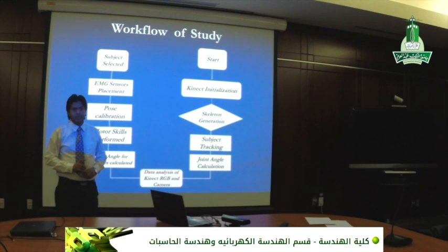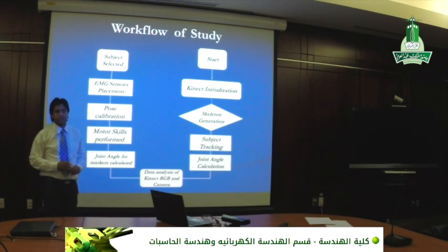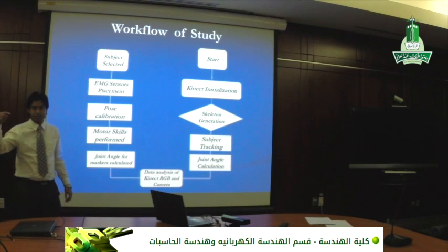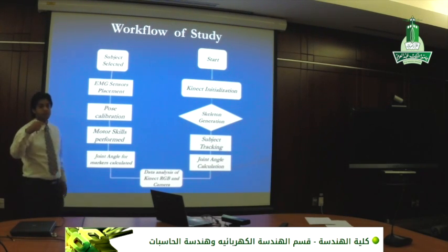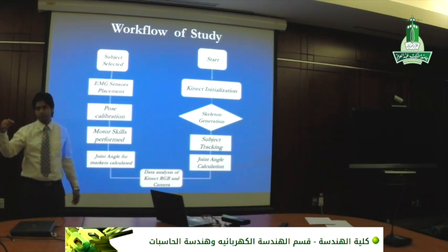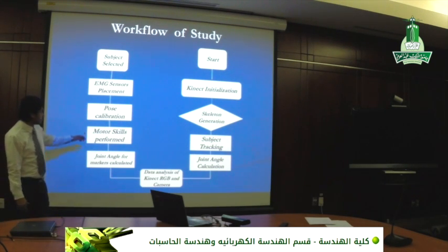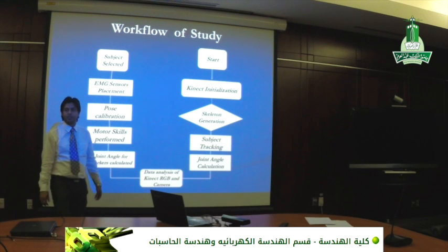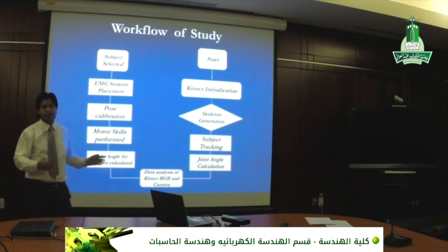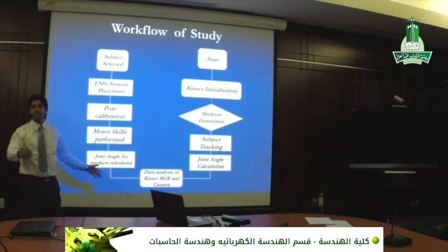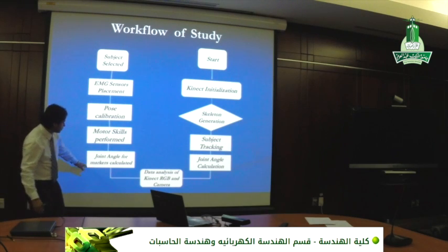What data do you get out of the EMG sensor? From the EMG sensors, we get the muscle firing activities, the value for the signal in millivolts. Those signals happen when the transition is happening from sitting to standing or standing to sitting position. And we get those data in an Excel file which we can process for our use.